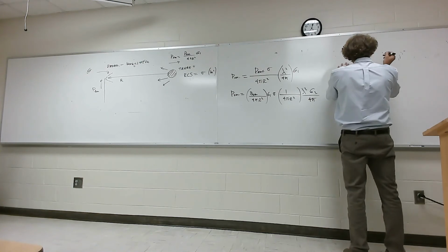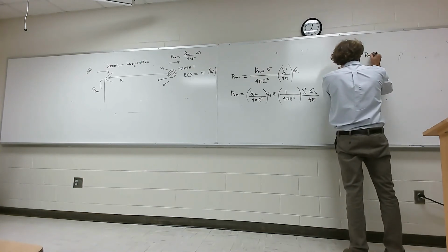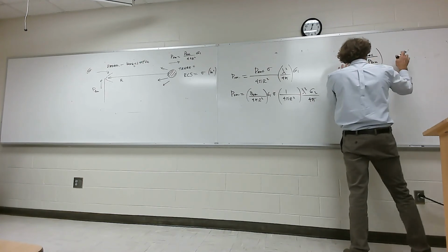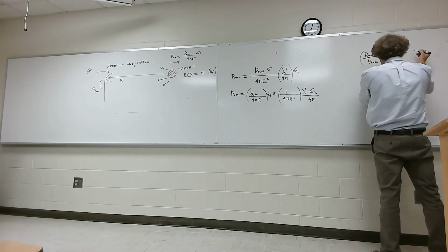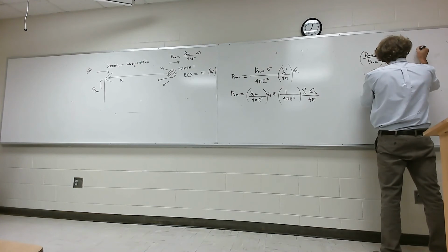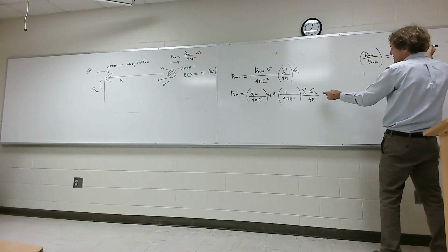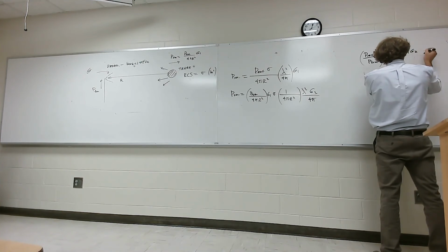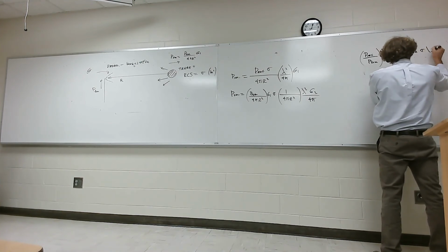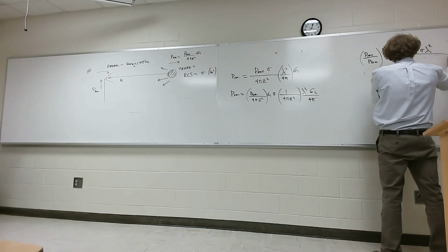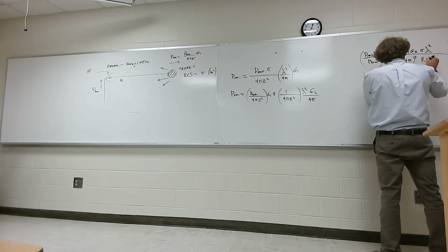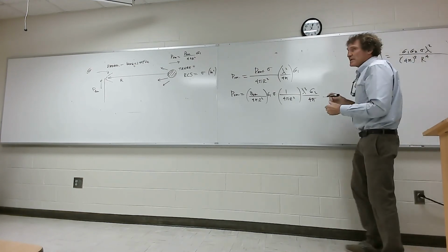So that's what happened. When they neatly condense things, they get this. You get a ratio of P received over P transmitted. This is similar to Friis. It is going to be equal to gain of the first antenna and gain of the second antenna, but they're one and the same in this case. But I can put gain of the first, gain of the second, then times sigma times lambda squared, which is what they normally do. They divide this by 4 pi cubed, and then by r to the 4th. And that's what he'll have in his book.